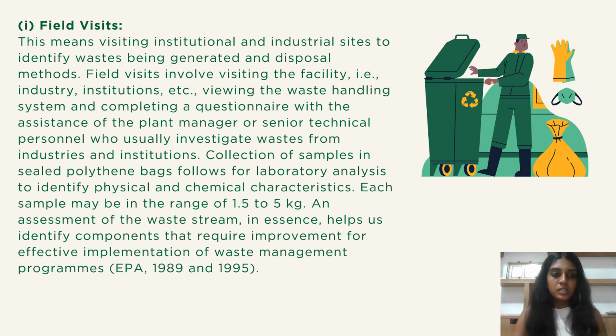Collection of samples in sealed polythene bags follows for laboratory analysis to identify the physical and chemical characteristics. Each sample may be in the range of 1.5 to 5 kilograms. An assessment of the waste stream, in essence, helps us to identify the components that require improvement for effective implementation of waste management programs.